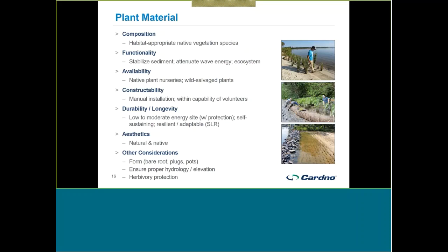In terms of their durability, they need to be paired with the right kind of toe protection depending on the energy of the site. They're appropriate for low to moderate energy sites with the right kind of toe protection. On real high energy sites, if you don't have vegetation growing there already, there's probably a reason why, and it's most likely related to the energy environment of the site.